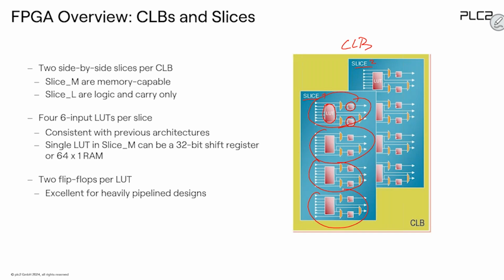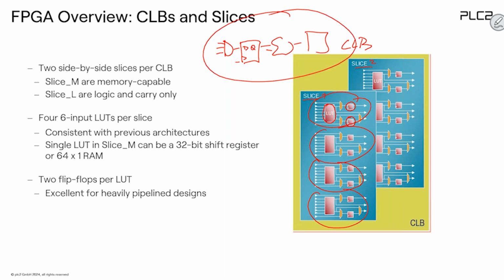All our FPGA designs, all of them, there is no exception, are constructed using such structures. We always have some gates connected to a register, and again some other gates connected to a register. This is the general structure of all FPGAs, no exception. And you see, this is the location where these structures are generated inside the slices. This means now we need to understand how I can make a description of my design, and how this description is placed inside the lookup table. The lookup table is the location where the gates, the combinatorial functions, are implemented. And the sequential elements are where the flip-flops or latches are realized.